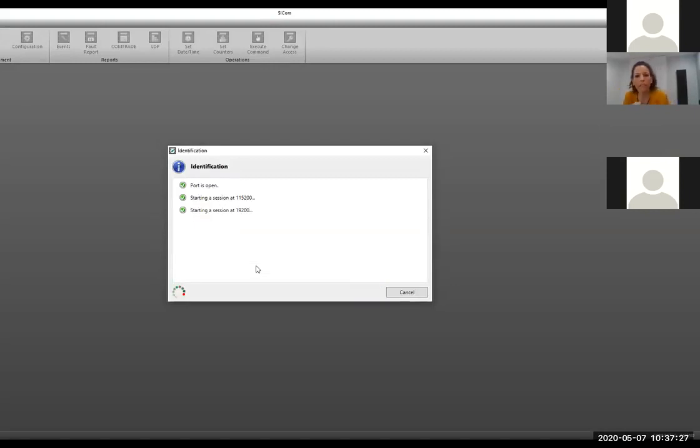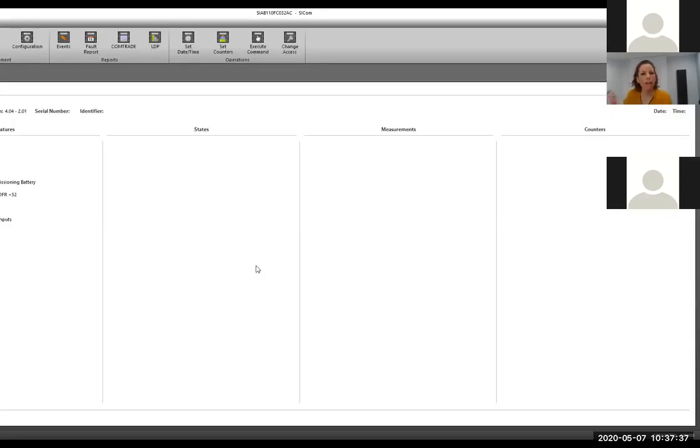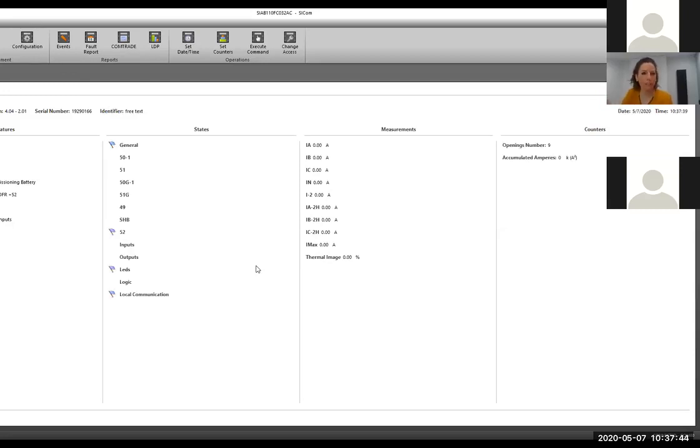It's very typical to have different settings groups with different settings for the maintenance task and for operation. So it's typical to prepare different tables, and in the installations, usually there is a switch to change from one table to the other.